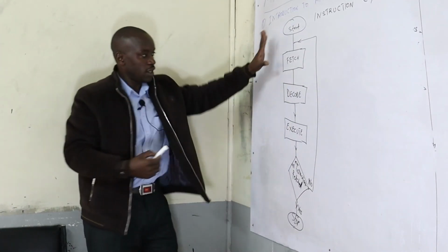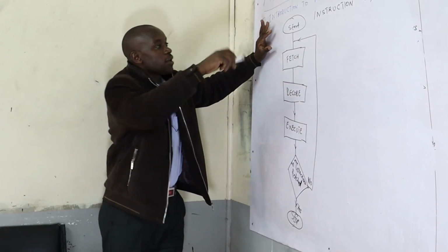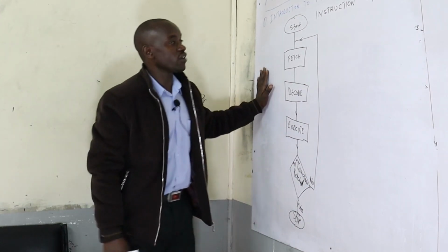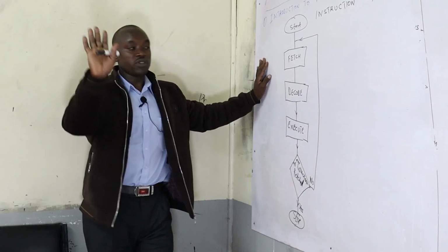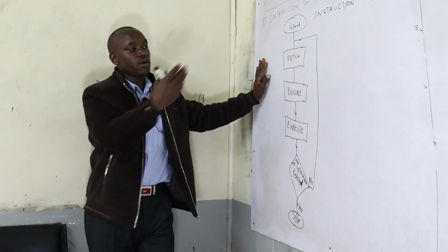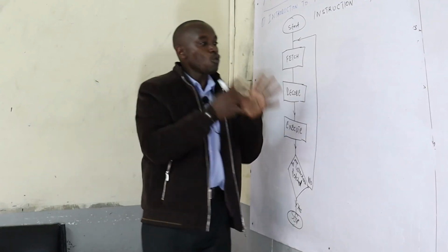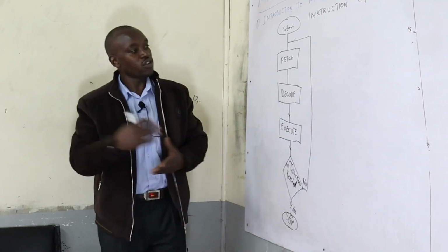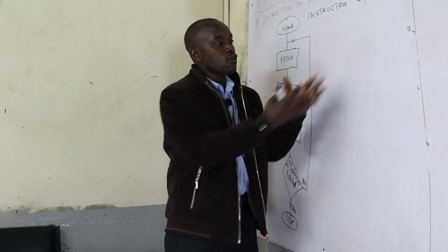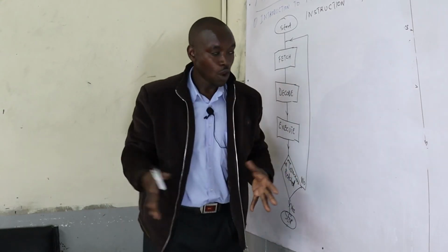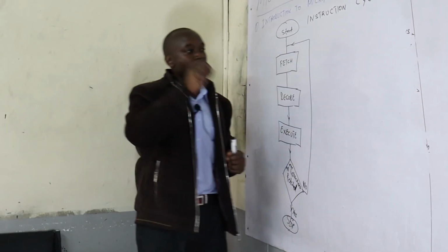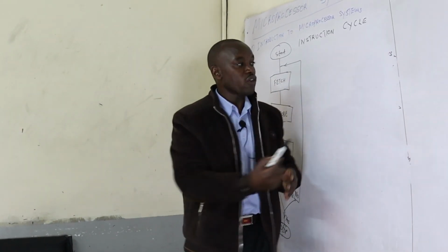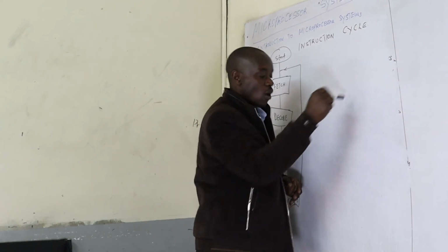now that we have understood the functionality and what is entailed in the processor, we shall move to programming. Before we enter programming, we shall talk about the different types of instructions, like data manipulation. I know this is where most students have problems in programming. We want to see things like move immediate, MVI, MOV, then we apply them and write programs. Once we are through, I have faith that people will understand that programming is easy once you understand what the instructions are supposed to do.